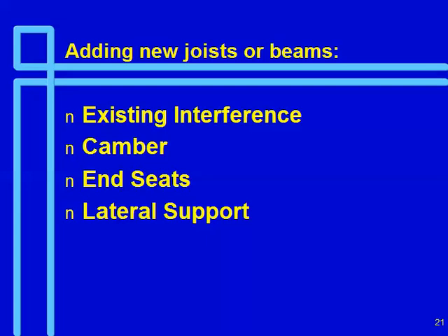And then the end seats. Remember I said on the beam you might consider making that end seat only 2 inches so the erector has room to shove it into place, so you then shim it. Same thing if you order a special joist for reinforcing. Ask for a 2-inch deep seat. They can give you a 2-inch deep seat. They'll find a way. Okay? So you think about that.